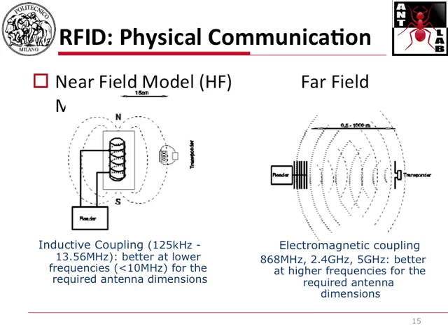Usually, inductive coupling is more effective at lower frequencies, which means that the current generated at the tag is higher if the frequency of the signal is lower. However, to get a good coupling, to get a good current level, the distance between the reader and the tag cannot be high, which means that it must be below 1 meter, roughly.